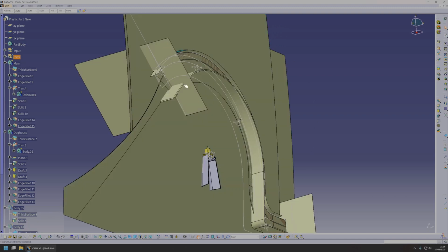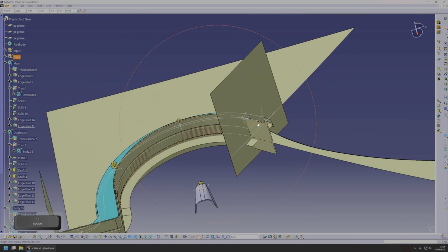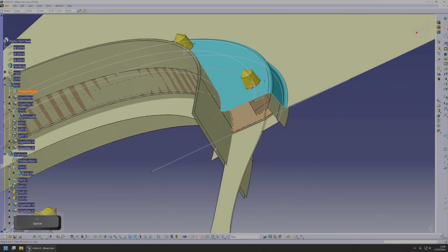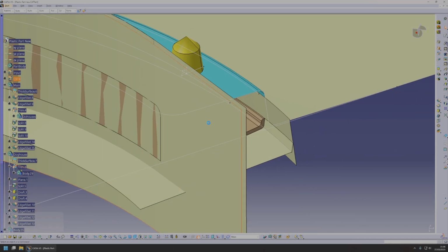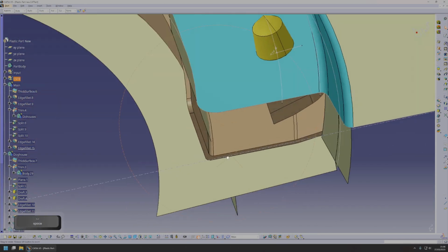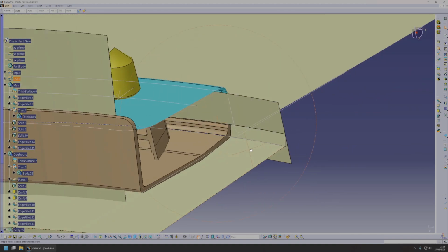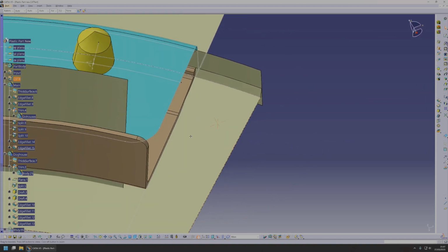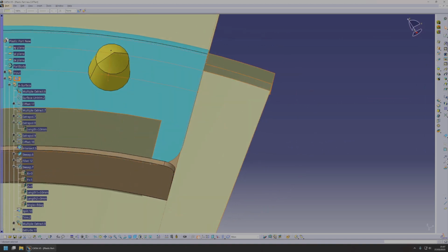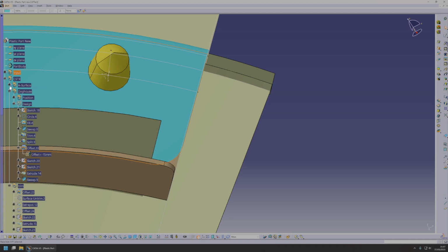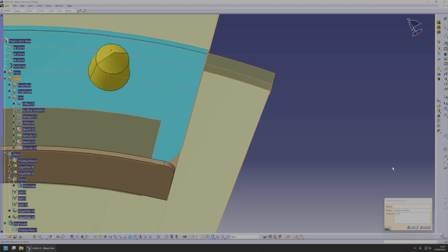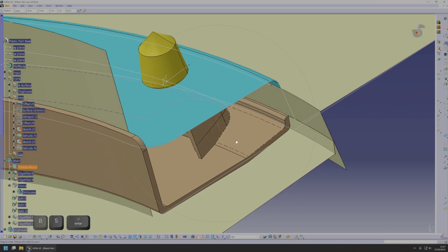Right, how to do some little final touches to the part. These ends need to have something here to close them up and stiffen them a little bit as well. So I will create another geoset here. I'll just call it, I don't know how to call it, maybe ribs. Yeah, that seems fine.